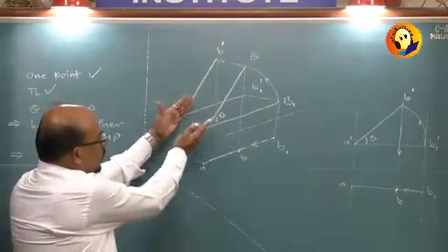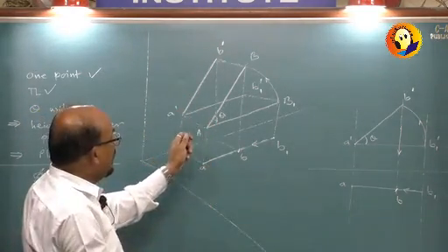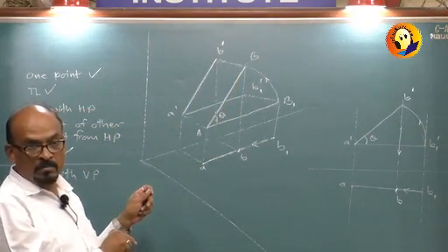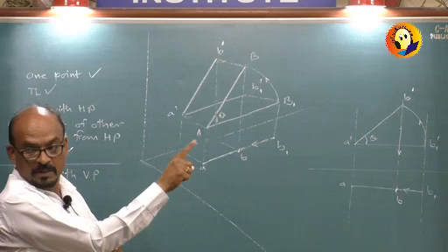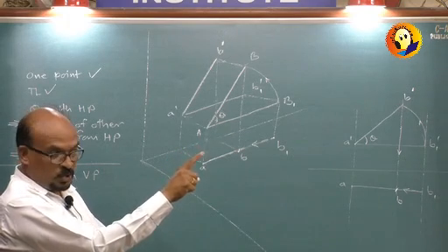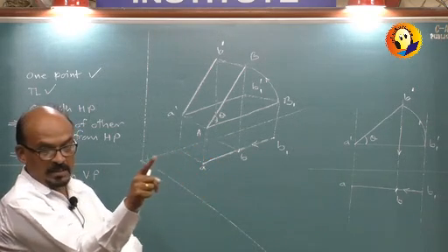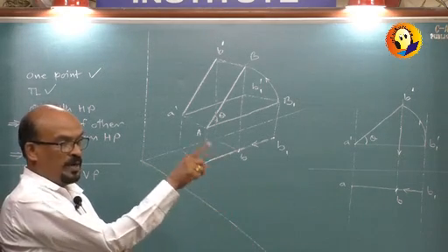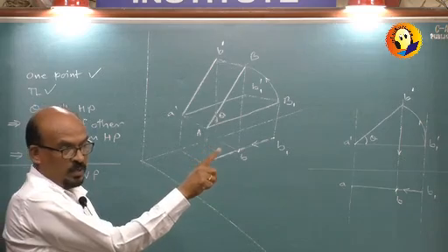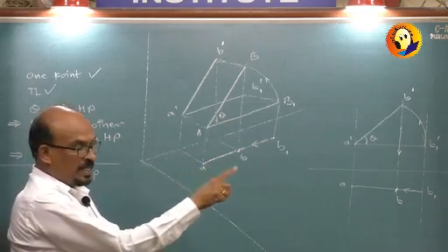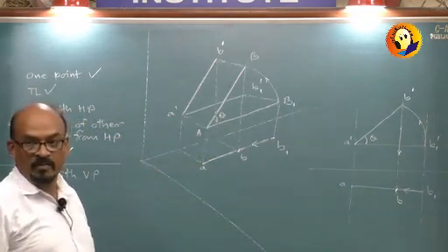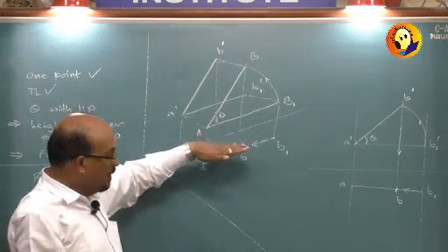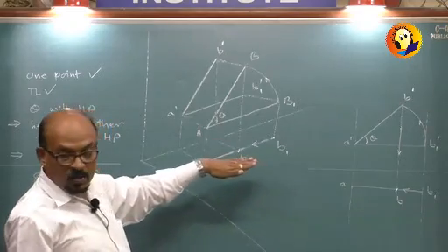now it is angle 0 with VP. If I am to rotate, I cannot let this point B come down, because the line has to make theta with HP. So it should not come down, and I should rotate it like this. It was initially horizontal. I have rotated it by angle theta, and now I should rotate it by phi. Now this angle phi will not be visible in the top view, because it is not the angle with horizontal. It is not seen in plan. It is not the true length.